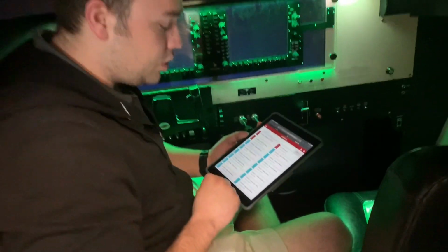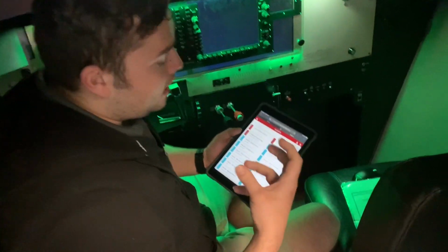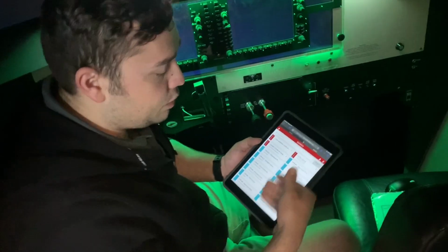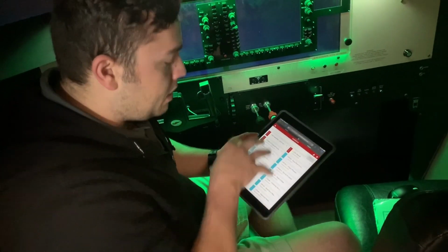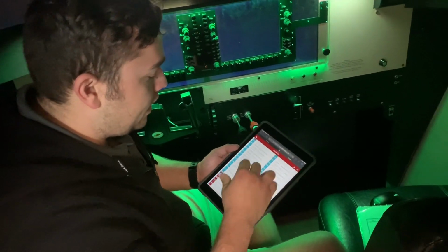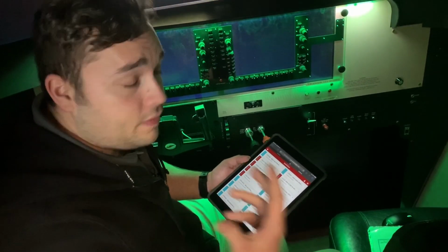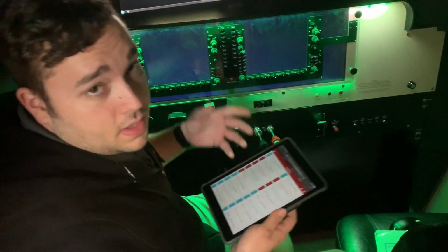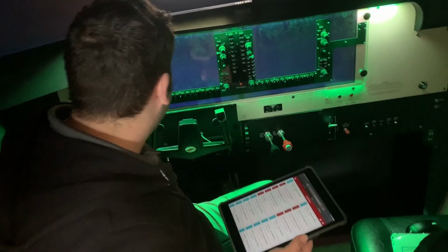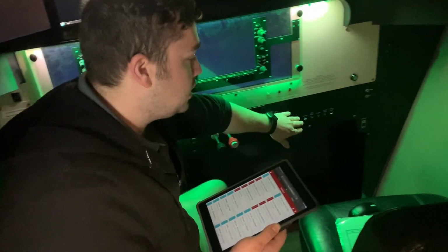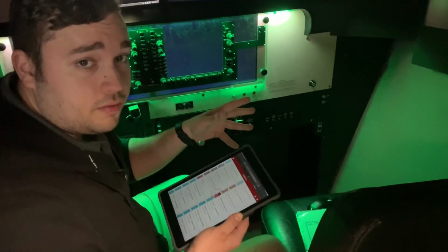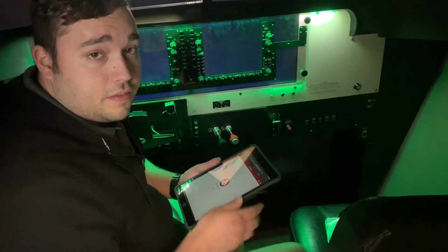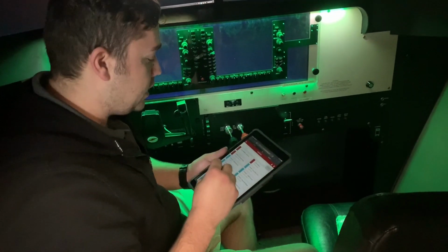So you should be connected to Redbird Wi-Fi, and you'd be able to tell if you weren't, if for some reason the navigator was not loading when you opened up the iPad. So from here, now that we have the navigator ready and armed, we're going to verify once again that the aircraft is set up back to a 0 stage. So we want to have everything shut off like we normally would, especially the circuit breakers. So I've got 2 popped out here, and I'll make sure that those circuit breakers are in before I load up any flights.